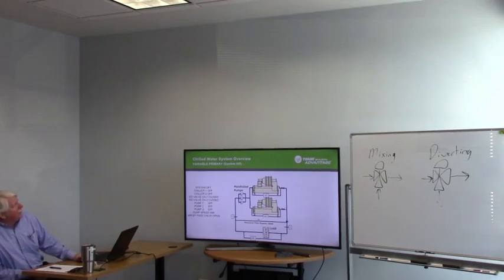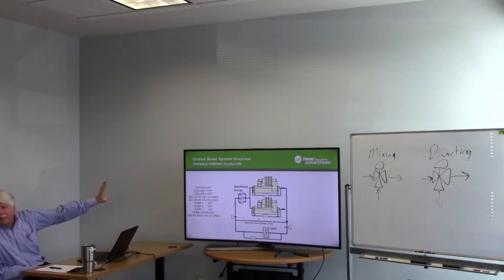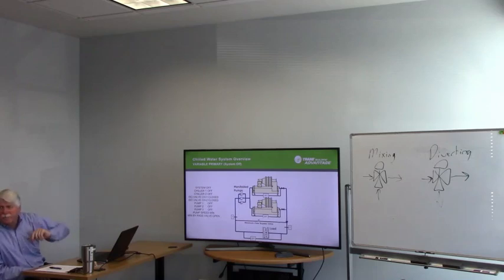What we're going to do is walk through a scenario where we start up a chiller plant. We need to talk about the sequence in which we do things, because this is very important. So we're going to start here, everything's off. Does anybody see a problem with any of this? The chillers are off, the ISO valves are off, the pumps are off, pump speed is at minimum, and the minimum bypass valve is open.